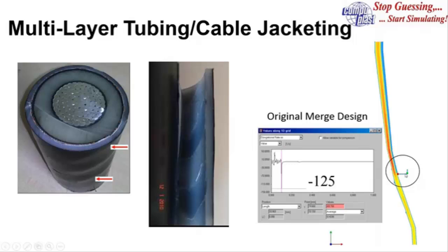And usually people will put a small gap on something when they want to have a very even distribution. They'll use the resistance of this channel to improve the distribution system somewhere back here, rather than optimize the distribution system and then optimize the channel. And what was happening here was slightly different than the wave example that you saw previously, where the material was accelerated too much. In this case, the deformation was negative. The material was decelerated too much. So it was coming through that gap rather fast and then slowing down tremendously.